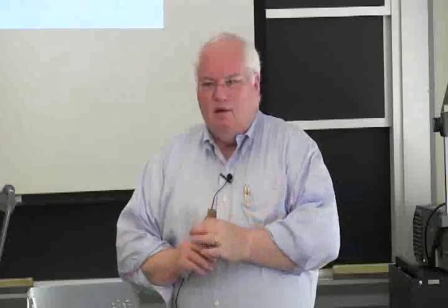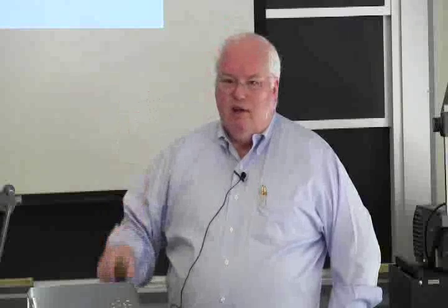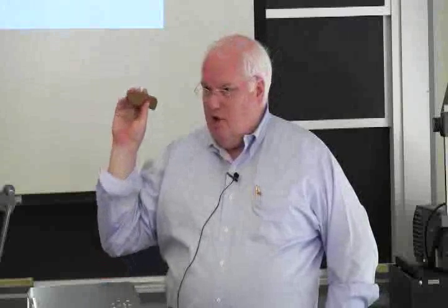In order to get the strength and the fine grain size and the ductility, they really needed about a 90% reduction. But their continuous caster couldn't make anything any larger than this. They had never made wire. This was twice the diameter, 4 times the cross-sectional area of any wire they had ever made. And I had 2 days to decide whether to accept $6 million worth of this product or reject it. And I rejected it. And then they sued the government.